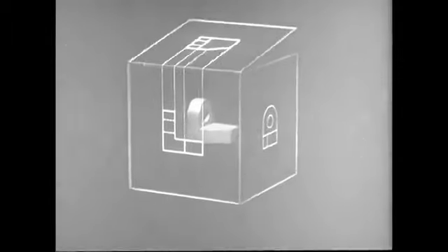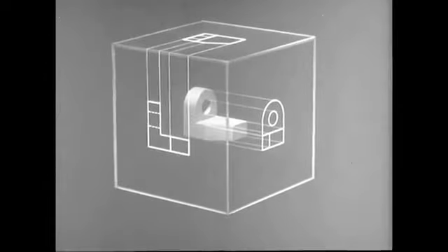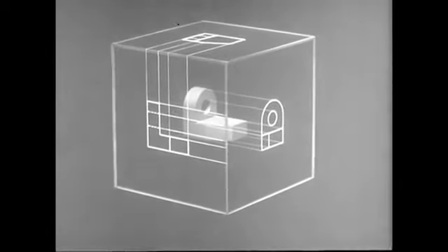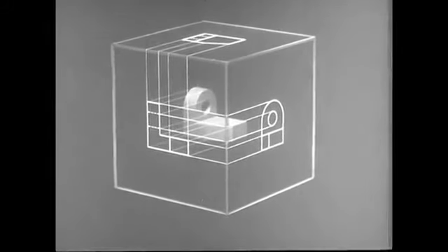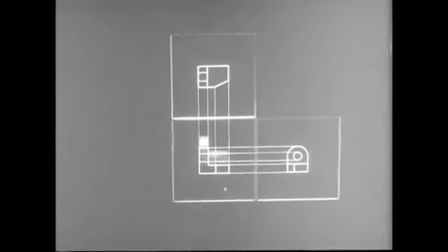In the same way, projection lines creating the side view have their images on the front plane, while projection lines creating the front view have their images on the right side plane. So, of course, the front and side views will be connected by parallel lines, and on the drawing paper, the height can be projected from one of these views to the other.